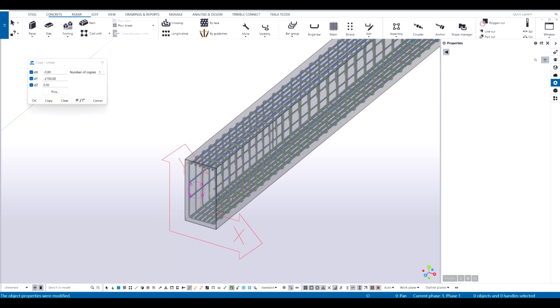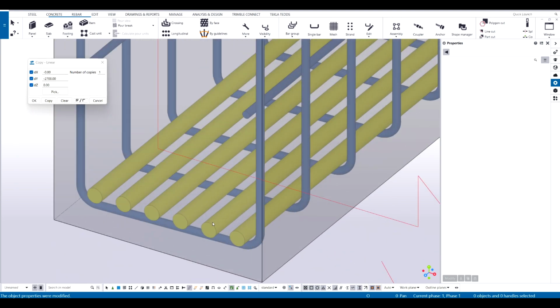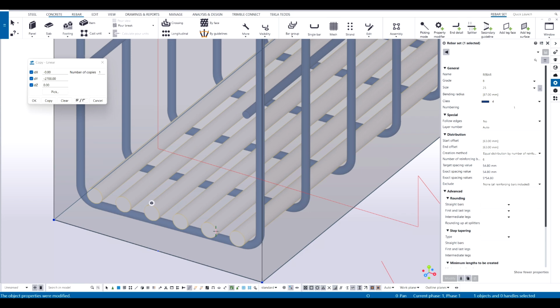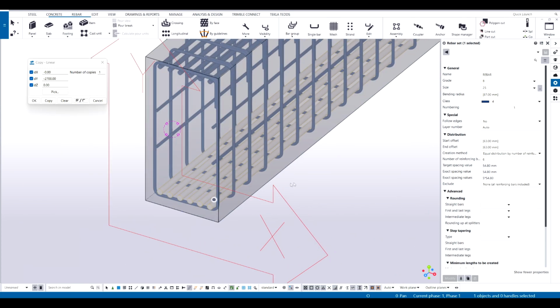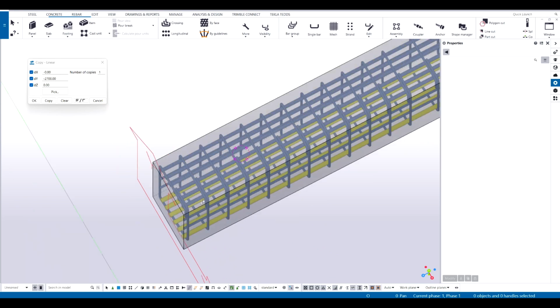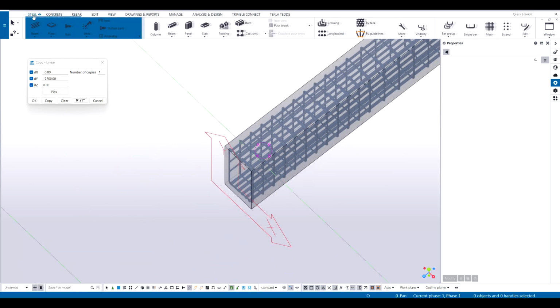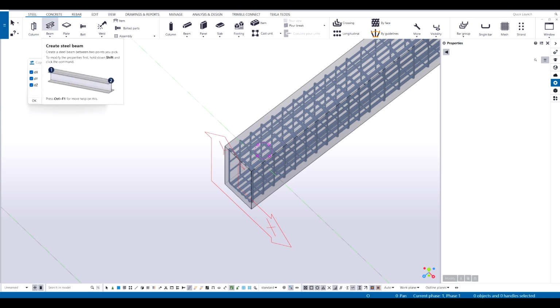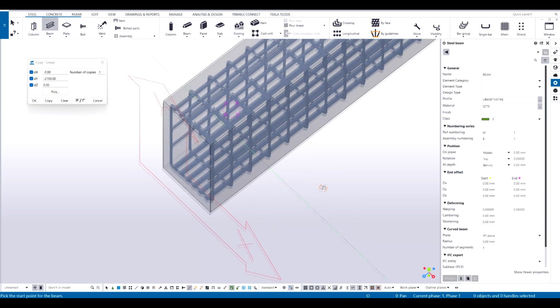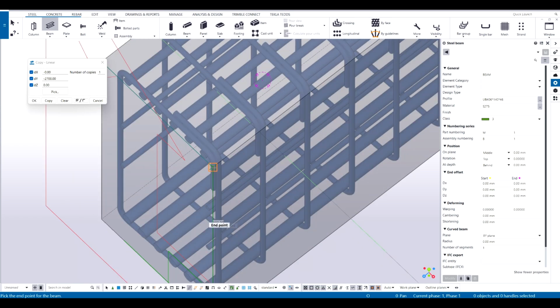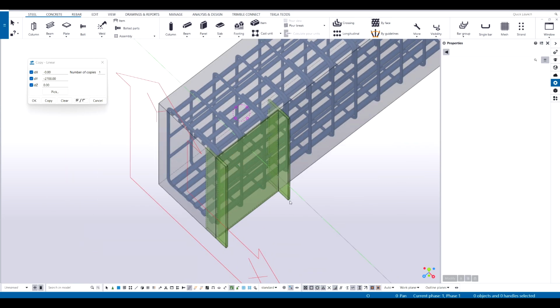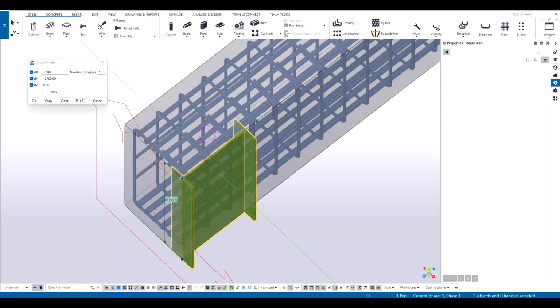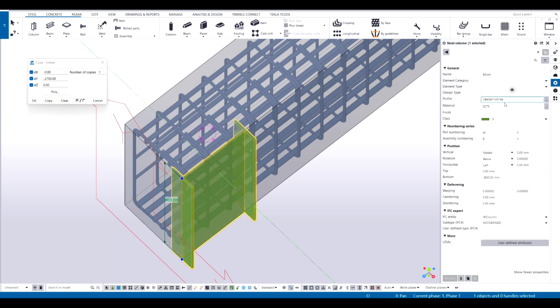Although there's a bit of detailing, like these are quite nearby, we'll ignore those errors for now. I haven't modeled a grout tube here yet, but let's put in a grout tube here. Let's take a beam. That's easy enough to modify. Let's just throw a beam here. For now, this beam, I'm going to select it and set it to 80 by 1.